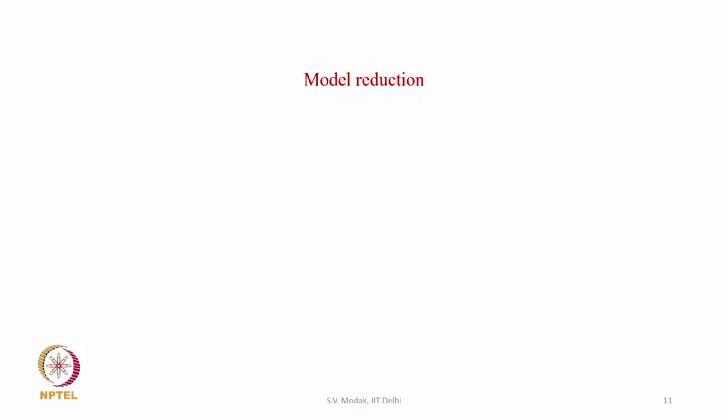So, in this application, therefore, the acceptable criteria will have to be more stringent. So, therefore, the acceptable level of correlation, how much can be tolerated and how much cannot be tolerated, depends on what kind of application for which the FE model has to be used. So, now we are going to talk about model reduction and mode shape expansion.